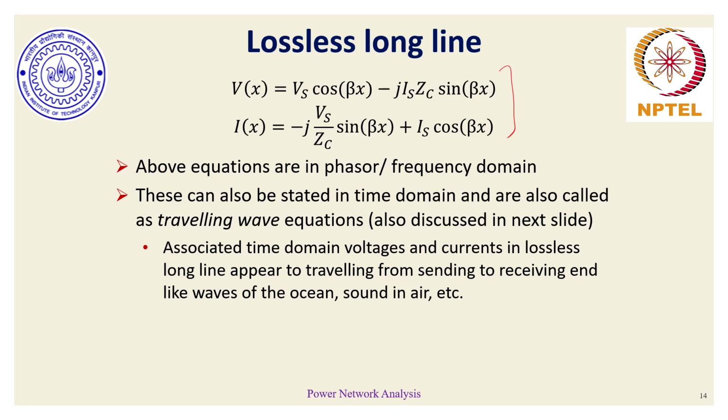These equations, or closed form solutions, can be represented in the time domain, where they would pertain to certain traveling wave equations, similar to a traveling wave in still water. It would appear that the associated time domain voltages and currents in a lossless long line are waves starting from the sending end, reaching the receiving end, and from there some reflection happens. So again we have a reflected wave, the way waves originate and propagate in the ocean or sound in air, etc.